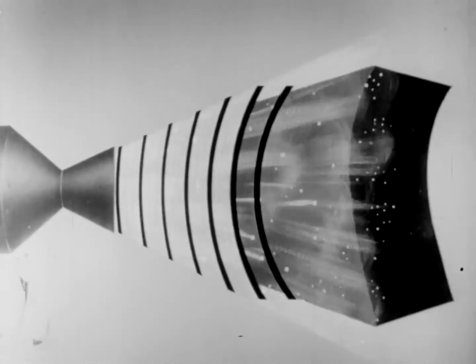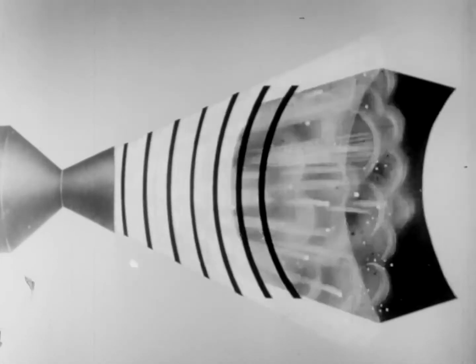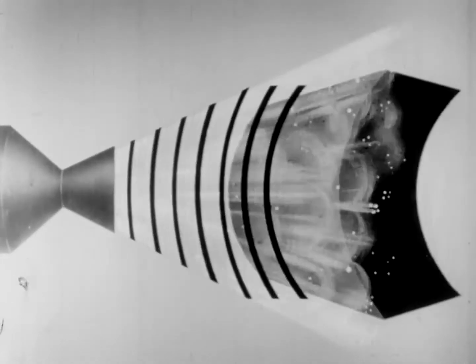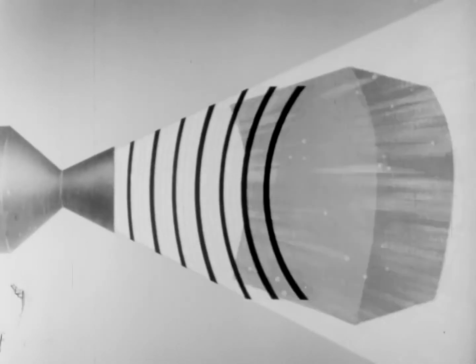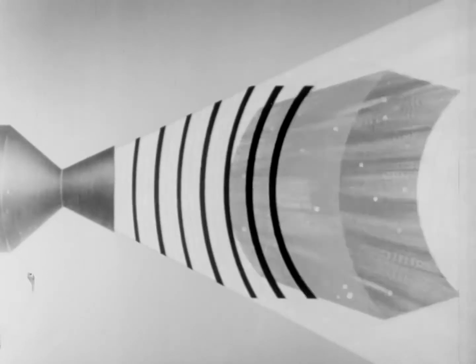Disturbances in gases are sound waves, and therefore must travel at the same speed as sound. Now, if the velocity of the exhaust gases were to remain below the speed of sound, then the disturbances they create could be transmitted back along the gas column to the rocket. But when the exhaust gases reach supersonic speeds, any forces traveling in the opposite direction would have to travel faster than the speed of the exhausting gases in order to have any effect on the rocket.